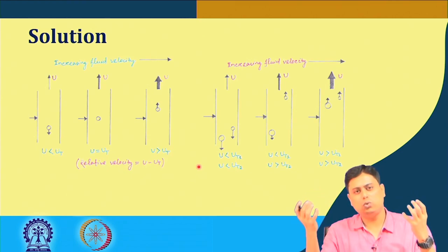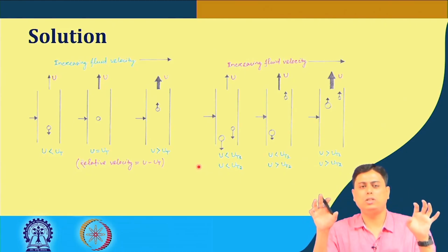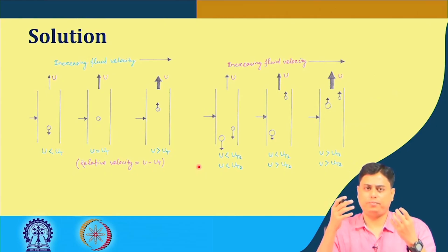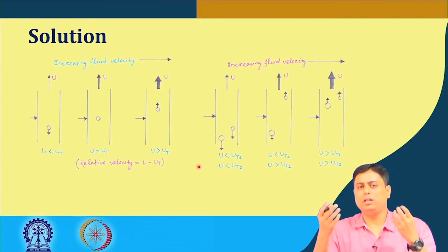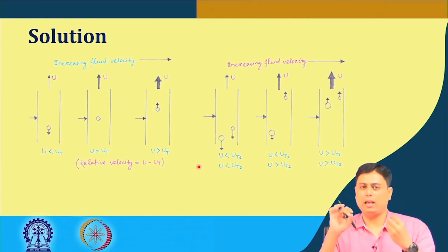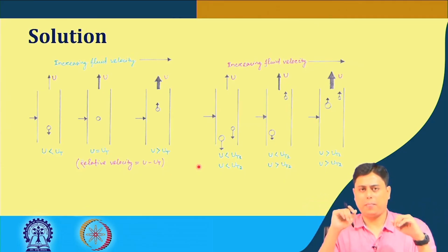If these two terminal velocities are clearly separated, then the whole range can easily be separated, because the heavier material with larger size will have the highest terminal velocity. The lighter material with the smallest size will have the lowest terminal velocity. There will be a significant gap there, but at the other end these two overlaps shouldn't happen.